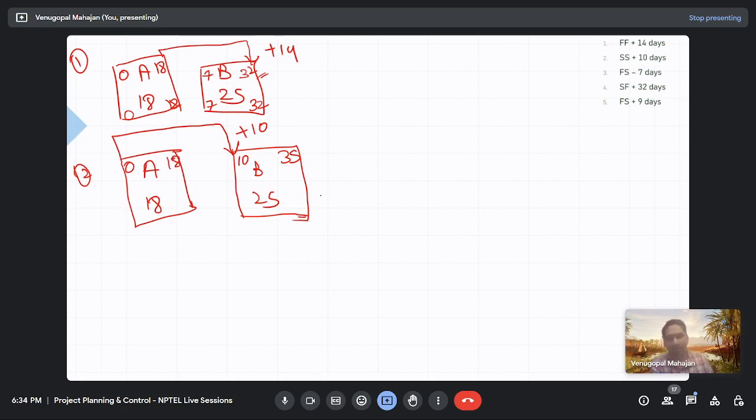So let's go backward also. What would be the late finish for activity B? 35. Late start, 10. So what would be the late finish for activity A? It would be 18, sir. Why? Because the relationship is start to start, sir. Okay, I have got 10, I have got 18. Can we finish activity A latest by 35?